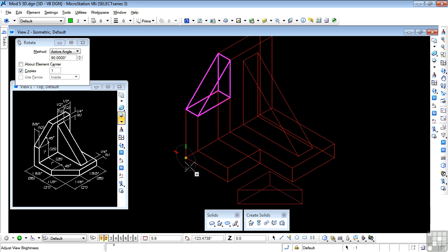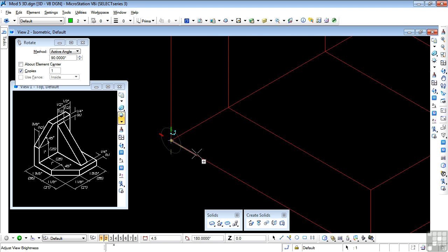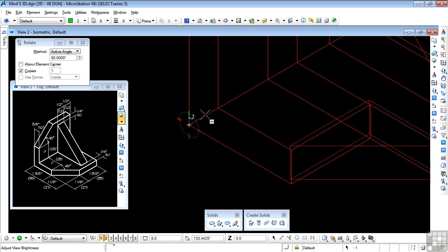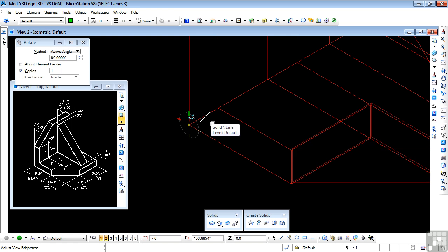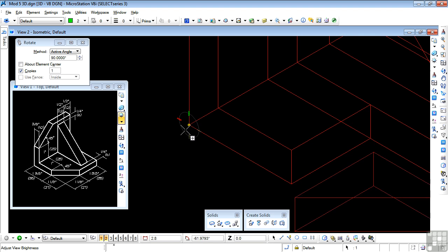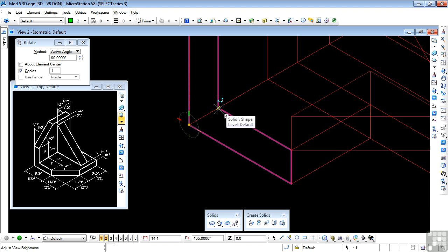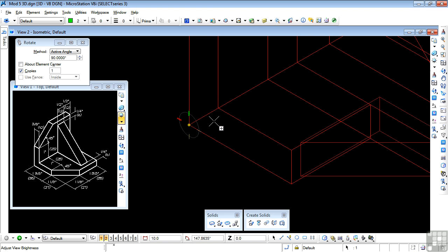So what this means is, if I look in closer here, I really need a rotation point which is halfway between this point and this point on this face. If I place the cursor approximately halfway, you'll see that the segment fits nicely. So I need a point halfway along. A couple of possibilities here. I could go the long way and draw a construction line from this point to this point and use that as a midpoint snap, or I can let AccuDraw do it for me.